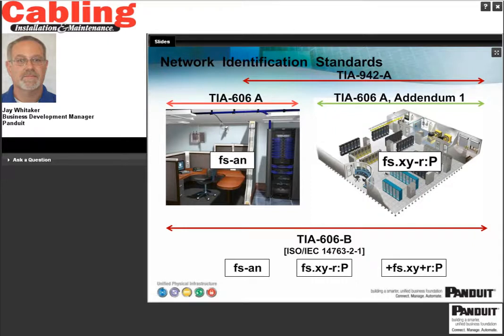In a Class 3 administration, the needs of telecommunication infrastructure with multiple buildings at a single site are addressed. In this class, we add the requirement for inter-building cabling, pathways, and access locations such as manholes and cable vaults. And then finally, in Class 4, we have multiple campuses that are being administered.